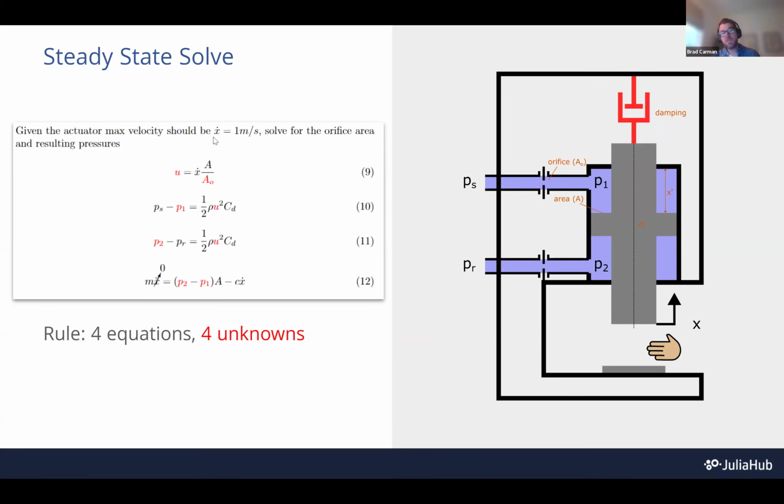So this is now going to be set as a constant, and everything else is what we need to solve. We need to solve for the fluid velocity. Most importantly, what is the orifice area? This is the thing we're trying to figure out that we want to purchase from a manufacturer. And we don't know exactly what the pressures are going to be to provide that fluid velocity. If you count, you can see that we have 4 distinct unknowns here, and of course, 4 equations.